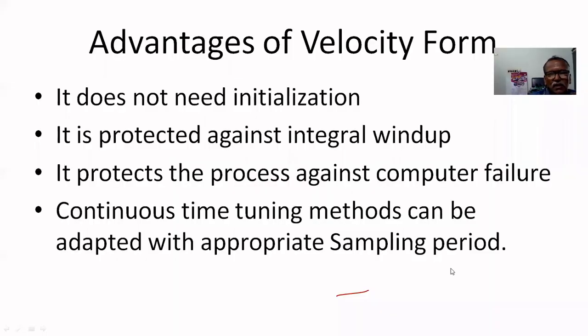Here, if you use the velocity form, there is no summation there. That's why there is no integral wind up problem. That is the first advantage: no integral wind up problem.